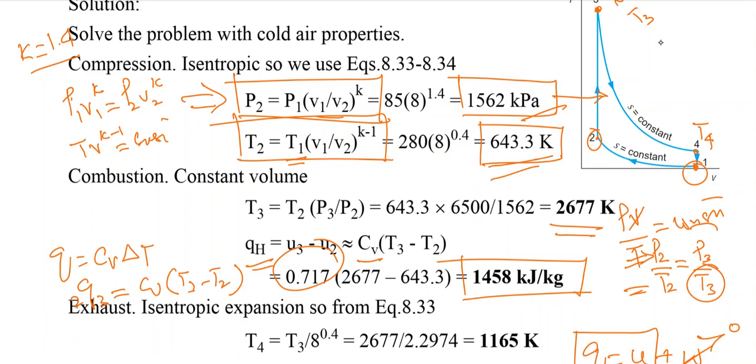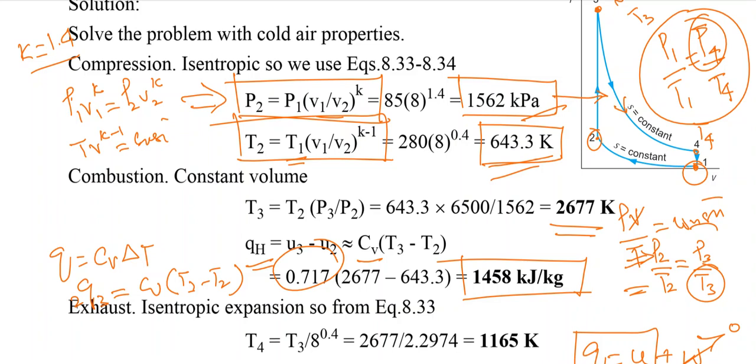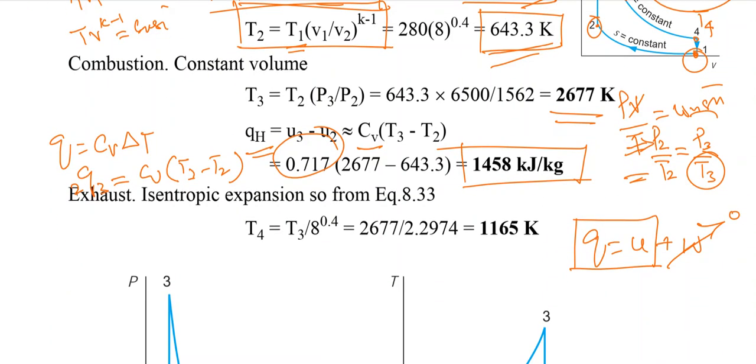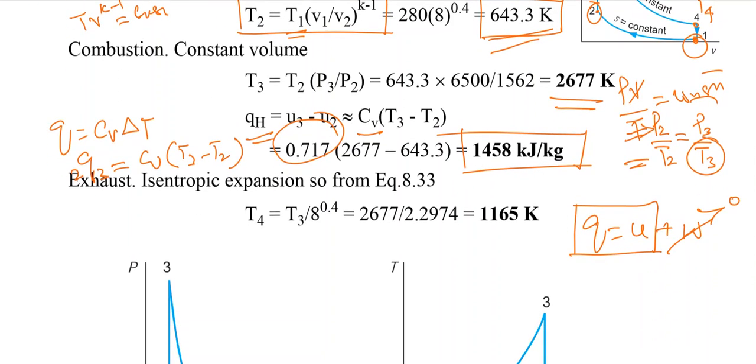So we can say P1 by T1 would be equal to P4 by T4. Sorry for that. Yes, we do not know the pressure P4 over here. So we can use the other equation, or we can come from state number 3 to 4. State number 3 to 4 is adiabatic expansion. So for the adiabatic expansion, again, we can write the equation in terms of volume.